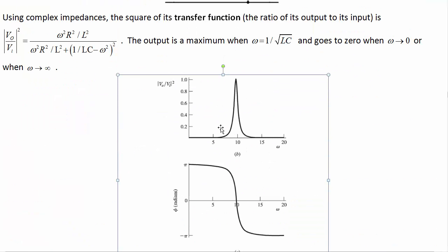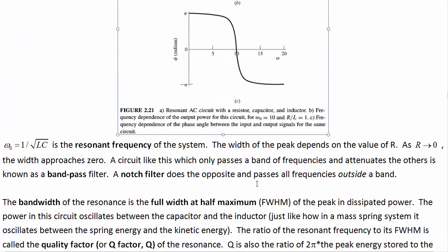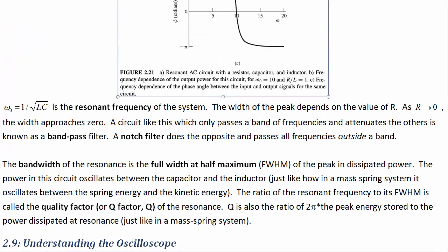You can see that from our definition of frequency divided by the half width. If we lower the resistance, then this gets narrower, and we have a sharper resonance, higher quality factor. Higher quality factor filters filter a more narrow range of frequencies. Quality factor is also called Q factor, or just the Q.